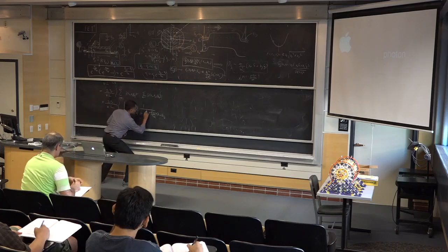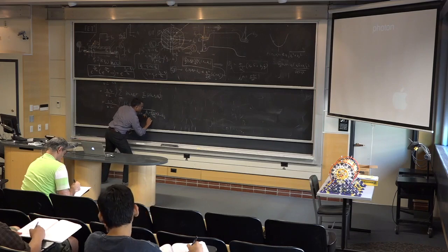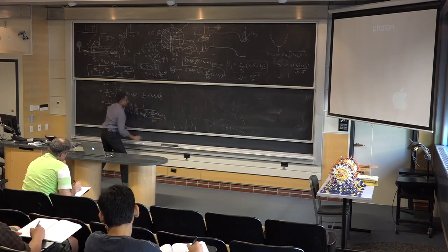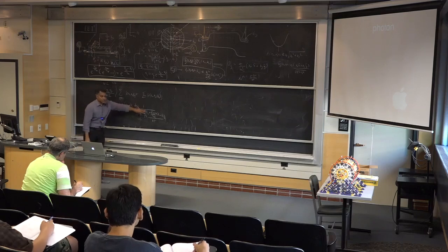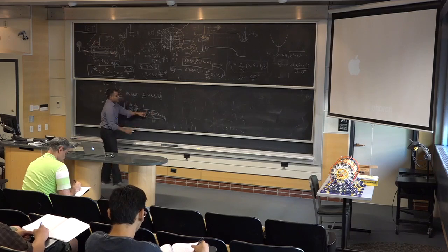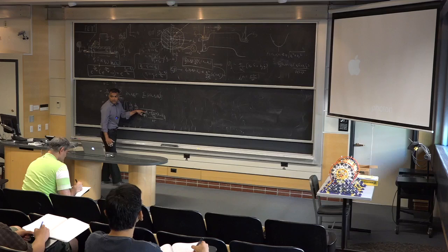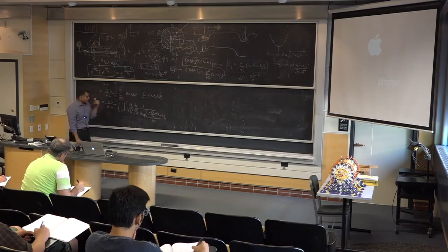Whole thing, let's write it as exponential here. Whole thing divided by kT. Right? You see, this is just the Fermi-Dirac distribution, but the first part here is the kinetic energy. The total energy, potential energy plus kinetic energy. Right? Band edge is the potential, and then the kinetic energy minus the Fermi level of the source. So that's the first term that's going to the right.